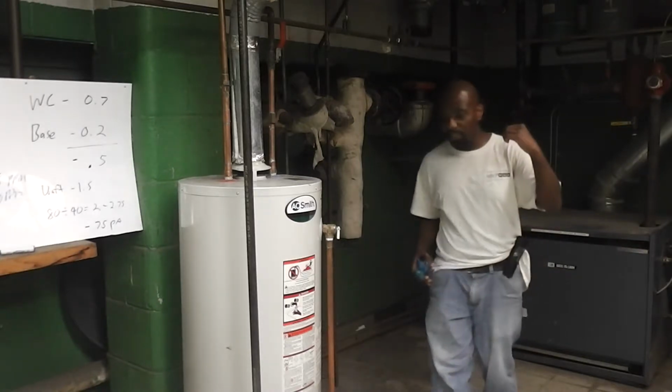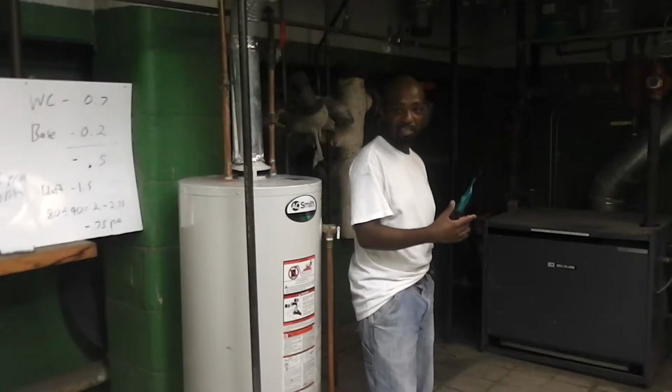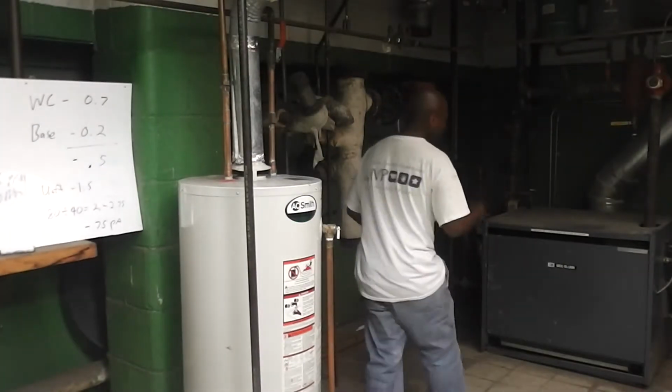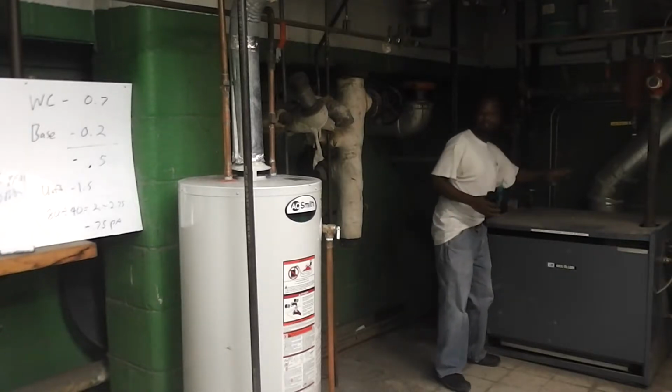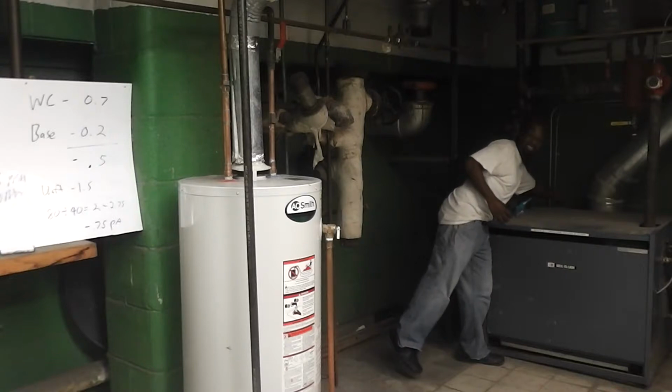Okay. So this thing is actually starting to turn on, right? I have to wait 60 seconds. I'm going to test the spillage on this particular unit. Now, if you notice on this unit, it's a bigger unit, but it's still atmospherically vented. So what's that mean? That means that beyond the diverter, which is this thing, is actually hollow.